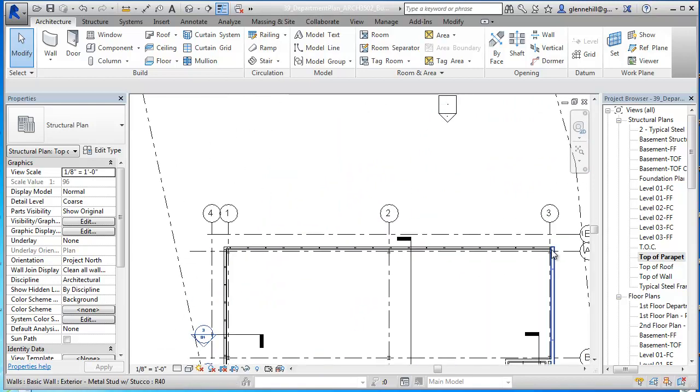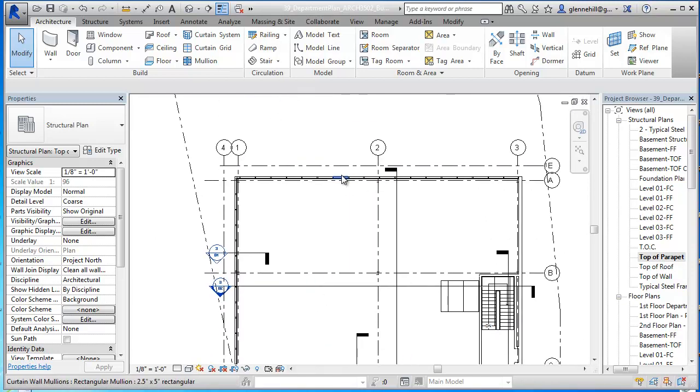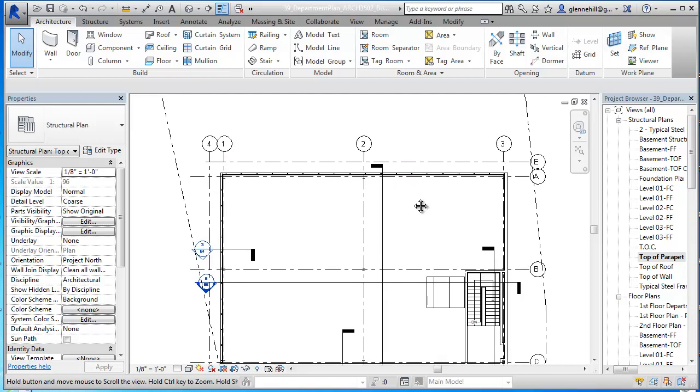From the sketch that I did, what I want to do is screen this from here to here to here and then all the way around to the other side, and that will cover this north wall and west wall. I'm going to put a slatted system on this side that I'll talk about in another video, and I'm going to put the mesh screen on this side. Now this is a north wall. Normally we wouldn't shade it, especially above the tropics, because the sun isn't going to really see this wall very often. But I'm going to treat it like it's a south wall and we need shading on it.